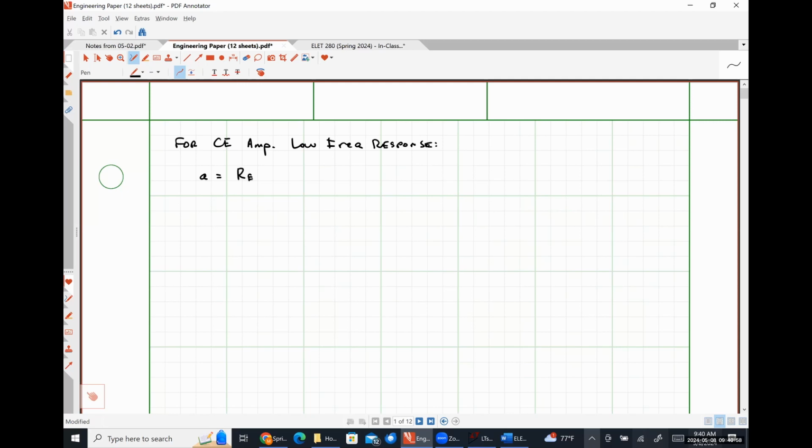I gave you RE times R sig times R pi plus R1 in parallel with R2, plus R pi times R1 in parallel with R2. What I want you to add to that is literally just multiply that whole thing by Cn times Ce. That should make the units of this ohms times seconds squared, which is what it should be for that particular polynomial.